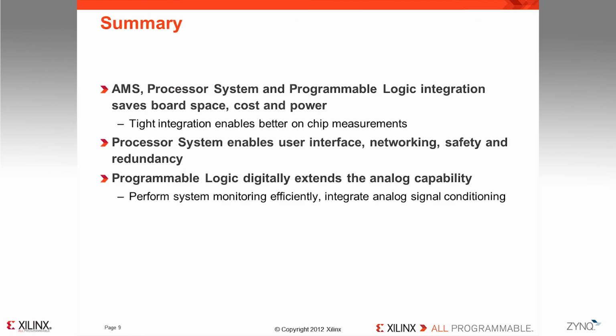In summary, the combination of analog, processor system, and programmable logic saves space, cost, and power. The tight integration enables better on-chip measurements. The processor system enables the user interface, networking, safety, and redundancy, to name just a few. And the programmable logic extends the basic 12-bit ADC by efficiently handling tasks such as system monitoring and integrating the analog signal conditioning in your processor system.